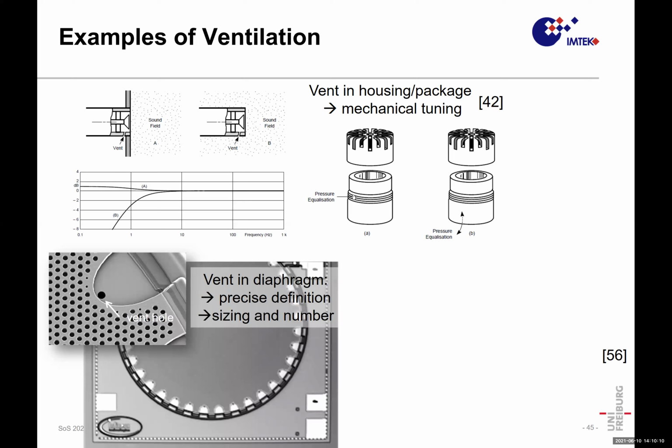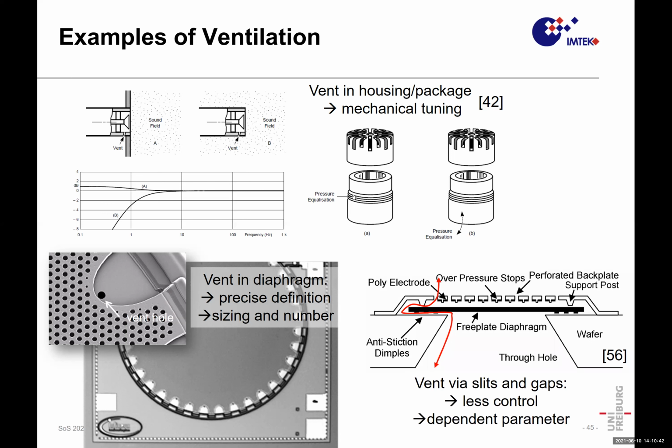In the MEMS situation, we have no issue in controlling the precision of holes. We can define such a hole by lithography with nanometer precision. We can multiply the number of holes by design. So we have a lot of means to control this ventilation, and with the ventilation we control the bandwidth, the corner frequency, and sometimes it's even important for speech recognition.